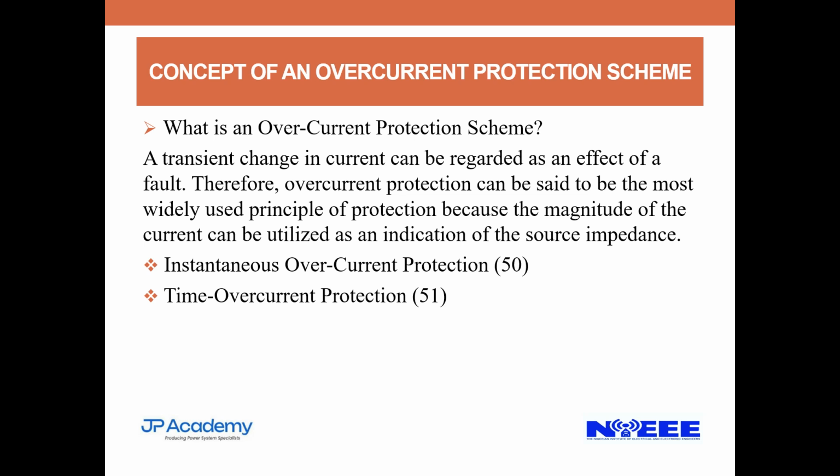But basically, let me just touch on it a bit. We have the differential protection, we have the distance protection schemes, we have the over frequency, under frequency, over voltage, and all that. Now, when it comes to differential protection, it is a unit type of protection scheme, and it is employed for a specific zone or a specific piece of equipment.